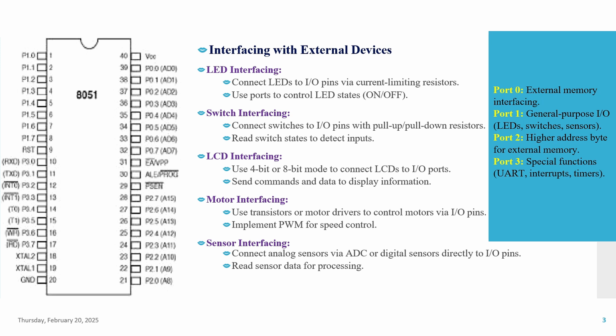Next one is motor interfacing. It also uses transistors or motor drivers to control motors via input-output pins. It implements PWM, that is pulse width modulation. We all know about this, that is to vary the speed of the gadget. It also needs a circuit diagram and sample code to run.